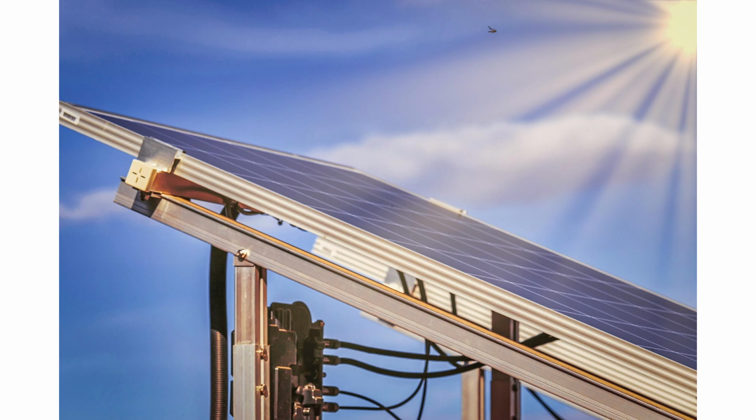Though that is the peak power output at standard test conditions, actual performance can vary significantly. Temperature may be much higher than 25 degrees, which reduces the efficiency. Rooftop solar panels in this region with hot climate are usually kept elevated above the roof to give good ventilation below the panels. That will reduce the rise in temperature of the solar panels while in bright sunlight.